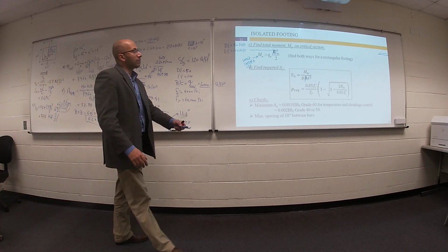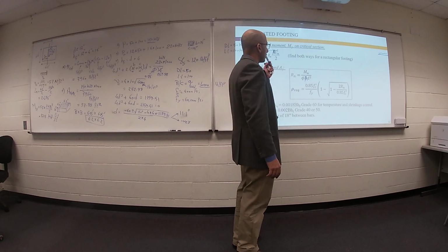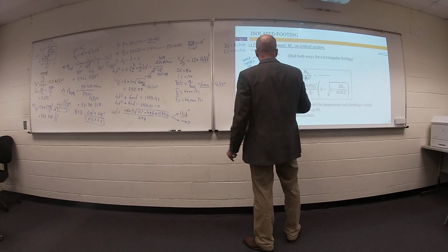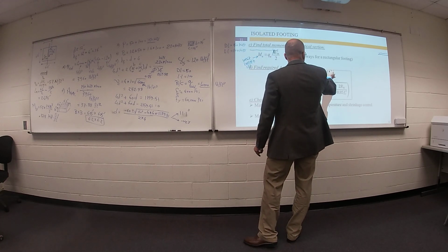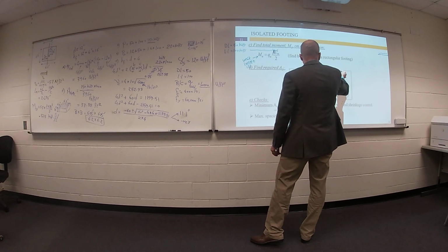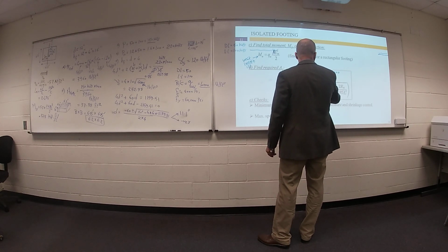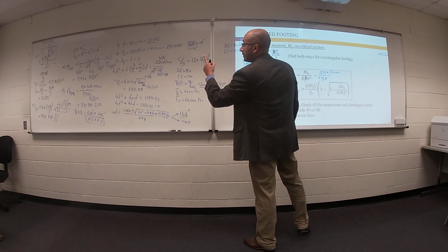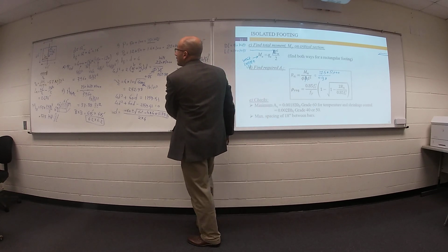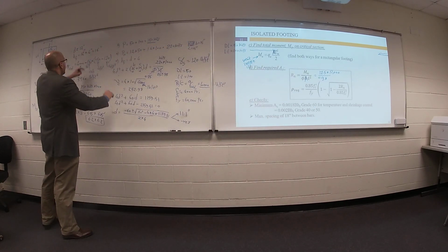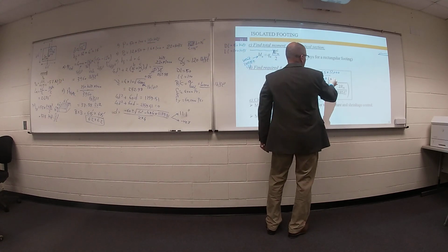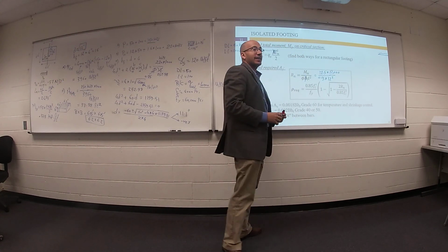Once you get your bending moment, go ahead and design. Your M ultimate is 17.5 times 12,000, divided by phi 0.9 times D squared. What is the value of D? Your D is 12 inch. Where did we get 12,000?